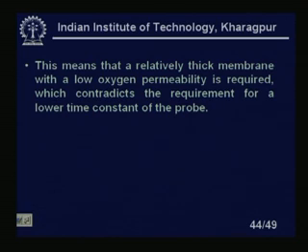This can be justified because in most of these dissolved oxygen measurements, we do not need a very fast response. For event controls, if you can measure every 6 minutes or every 10 minutes, that will suffice. Same thing with wastewater treatment plants, we do not need that fast. If you have a sensor which can measure the partial pressure of dissolved oxygen or dissolved oxygen concentrations every second, that does not make any sense.